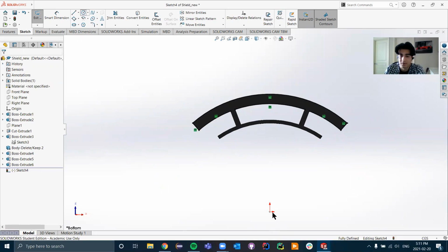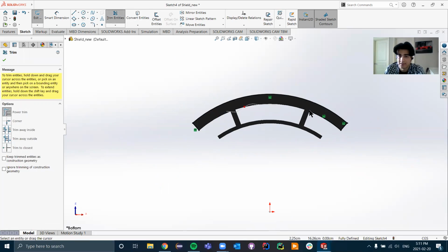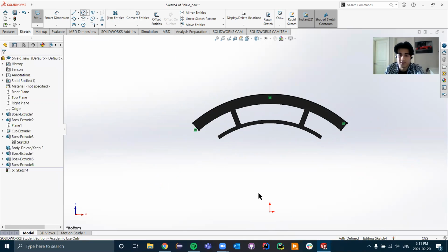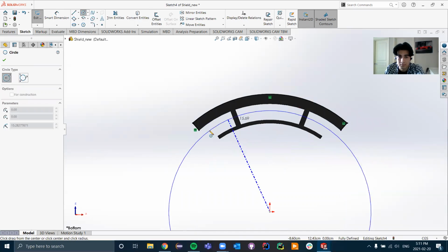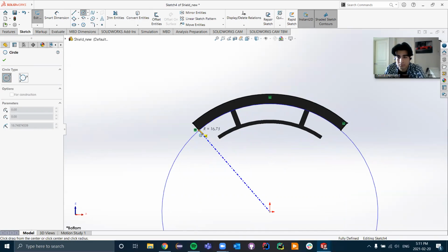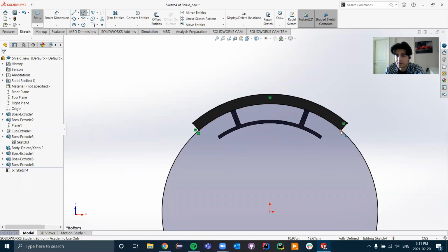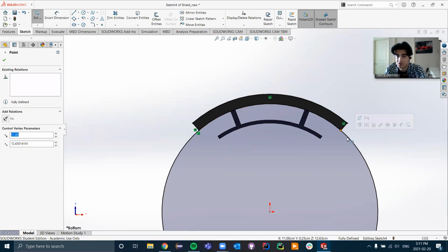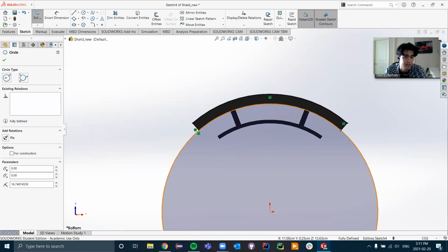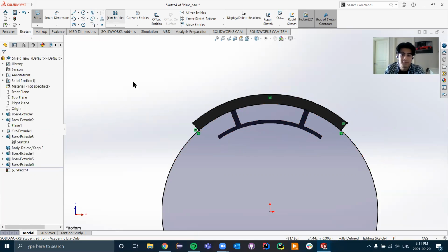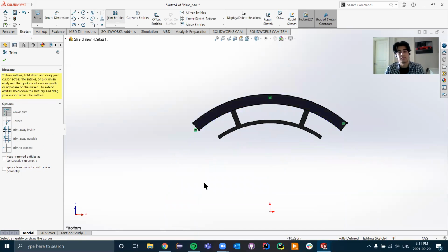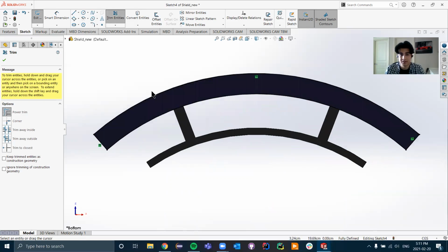And if we want to make this one entire solid line, I'm actually going to get rid of these different ones in the middle here and create one solid line with a circle. And just ensure that it is coincident on the other side too. So shift click on the bottom edge of that side and press coincident. There we go. And then get rid of the excess. Perfect. We have a closed contour here. You can see it's slightly shaded blue.